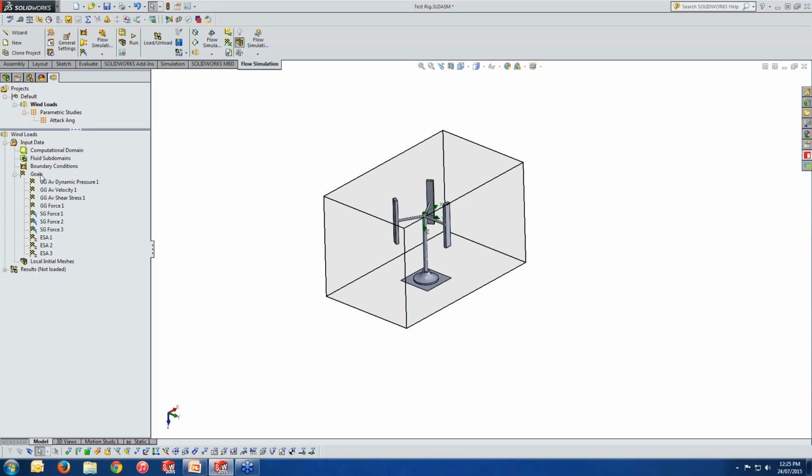This comes down to a series of goals you simply define. If you are interested in looking at the convergence and variation of a parameter, then you can right click on your goal. Either you would like to trace it globally, or at a point, or at a surface, or over a volume. Also, if you have your own equation to be traced, then you can insert the equation code. This is exactly what I've done.